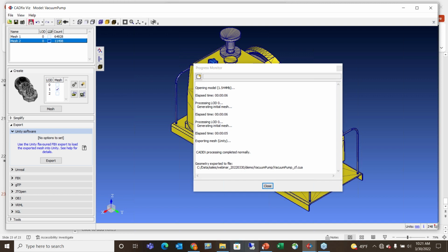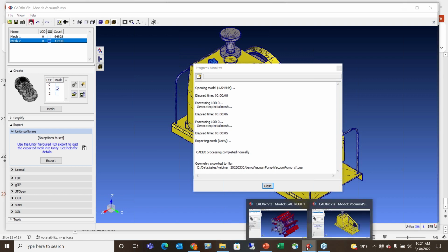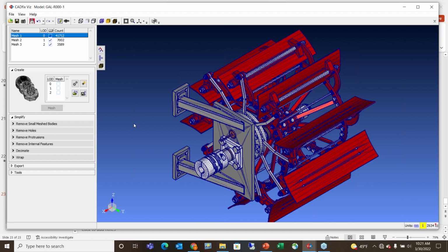And then ultimately, a lot of the payoff comes down to decimating the model. Going to open up the geometric change a little bit here and accept as much as a 4 millimeter change in geometry. And in this case, I'm using a percent reduction of 70%. And we'll see how close we can get with that.